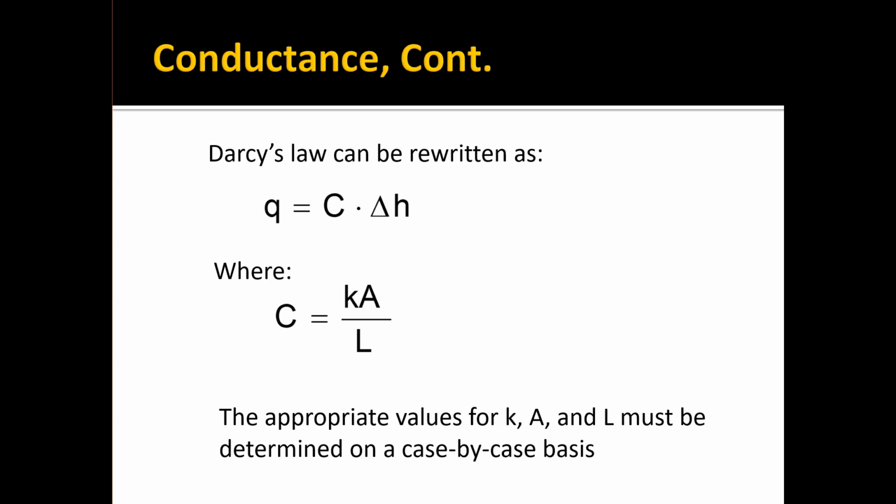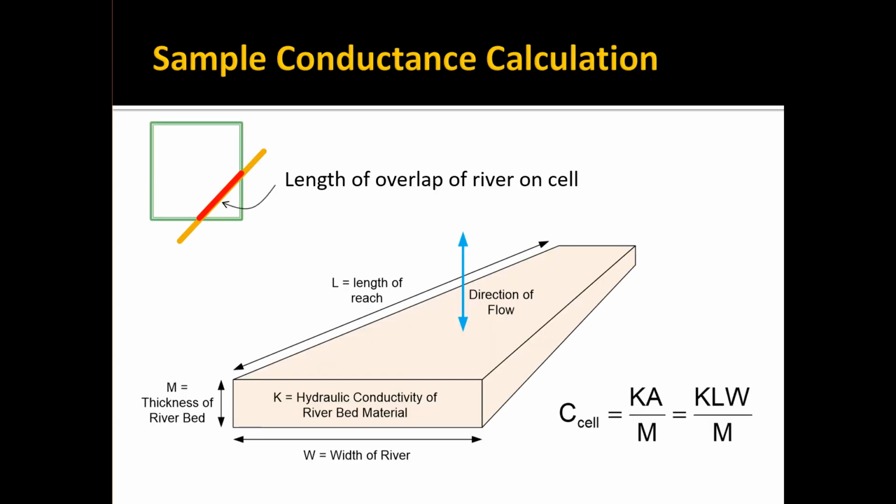And so the appropriate values to use to calculate your conductance, the values of K, A, and L, you just have to determine on a case-by-case basis, based on your understanding of Darcy's law and what that means.